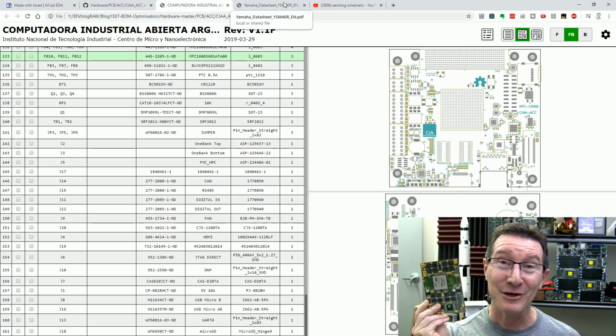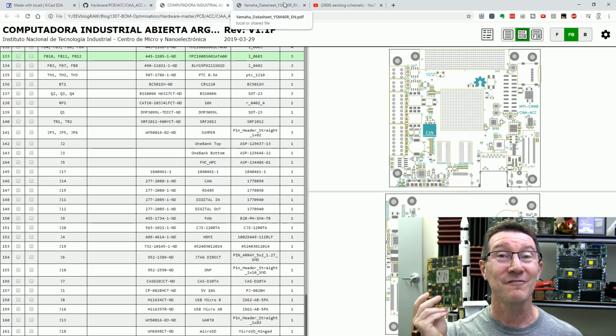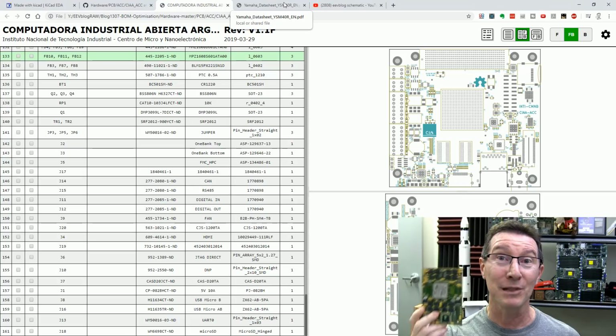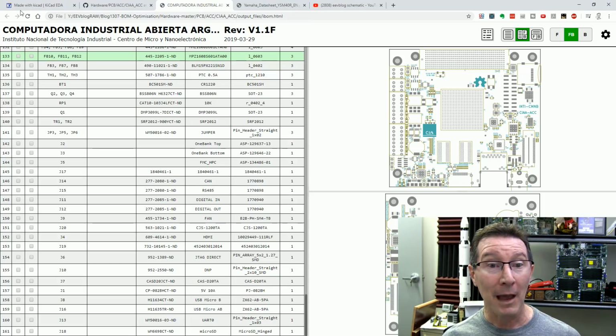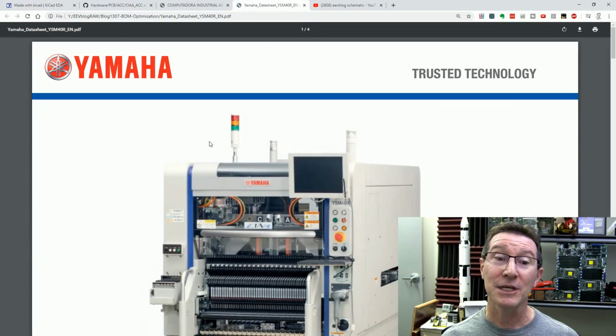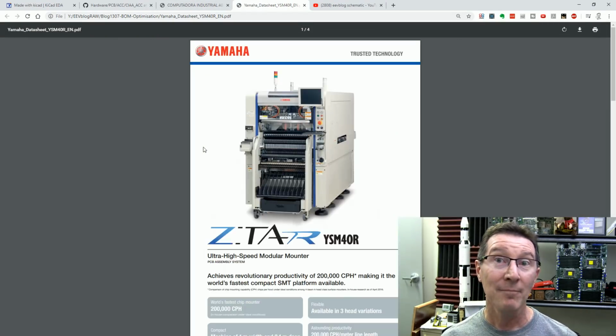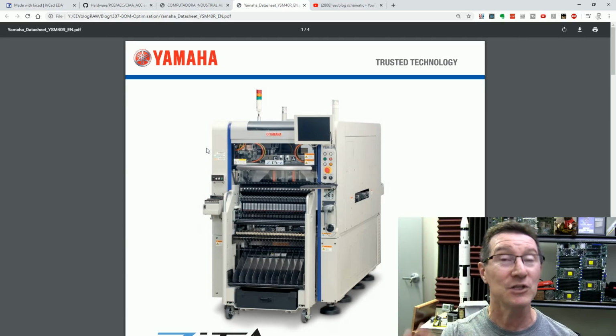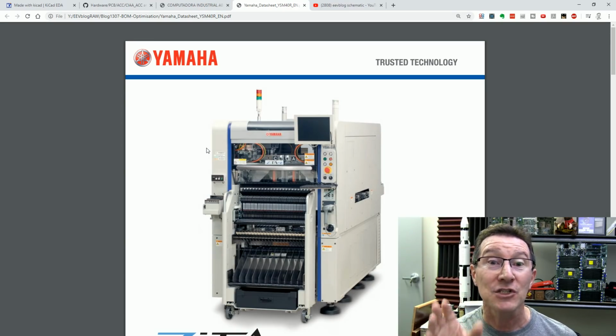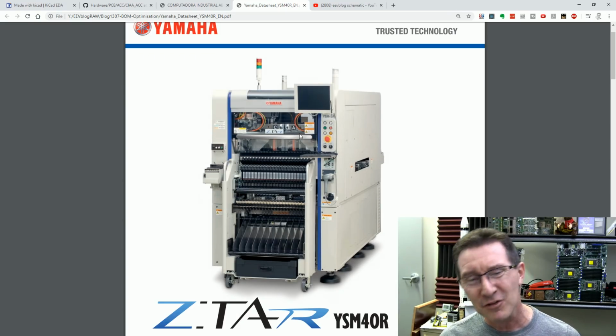Anyway, you're going to get your widget. You're designing this thing for high volume manufacture. It's going to be pick and place machine assembled. Well, you've got to know all about pick and place machines, in particular what your particular assembly house has, and you should actually choose and talk to your assembly house even at the design stage, even when you're designing the schematic, if you're serious about this sort of stuff.